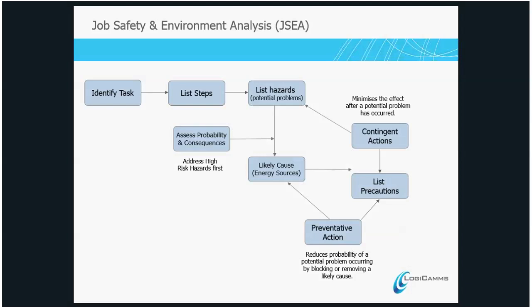You list the steps. That's the basic steps, the stages of the task, for example, start the machine, load the machine, clear the blockage, and unload. These will be our basic steps. Then the hazards for each of these individual steps. And lastly, the controls, which is the step-by-step instruction on how to safely carry out the task, including equipment required, the PPE to be worn, and any special precautions based on the site requirement.